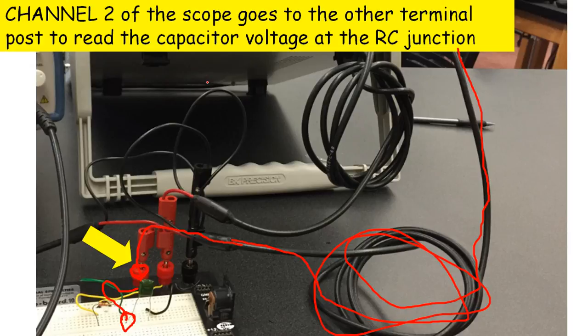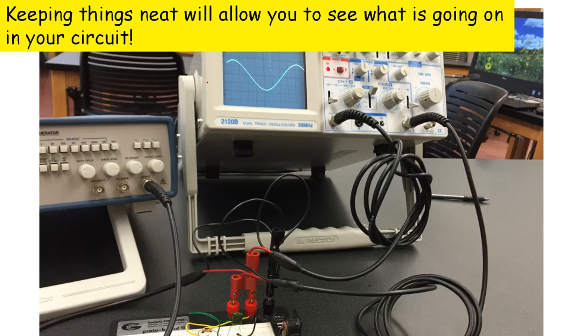So now channel 2 is measuring the voltage across the capacitor, see? And the ground from channel 2 is coming in here into this little tree, and all those are sharing a common ground, and that's very common in electronics land.